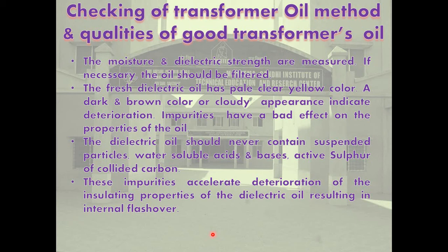The moisture and dielectric strength are measured in oil. If necessary, the oil should be filtered. The fresh dielectric oil has pale clear yellow color.